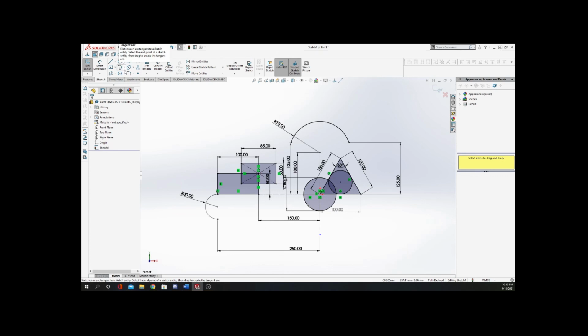And then finally, and I think I'll go to a clean drawing after this, we have the 3-point arc. The 3-point arc is pretty easy to explain as well. You click, and you can see that's the first point in my arc. There's the end point in the arc, and then this is the middle point in the arc.